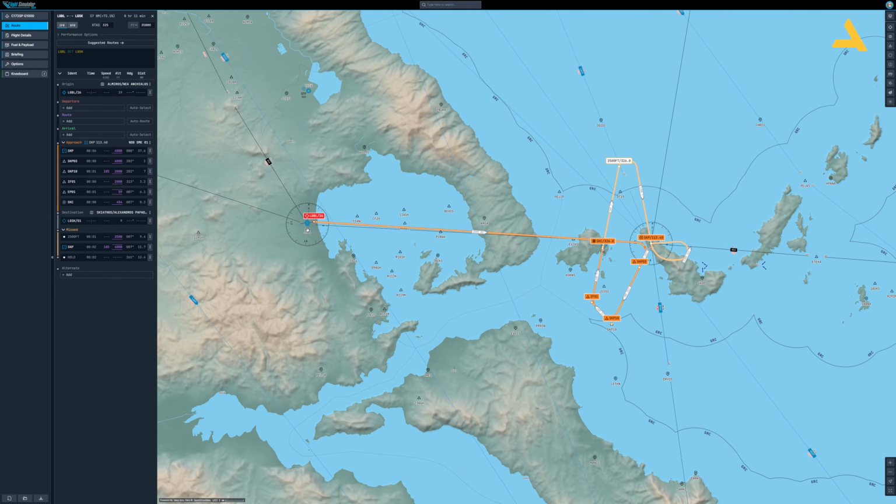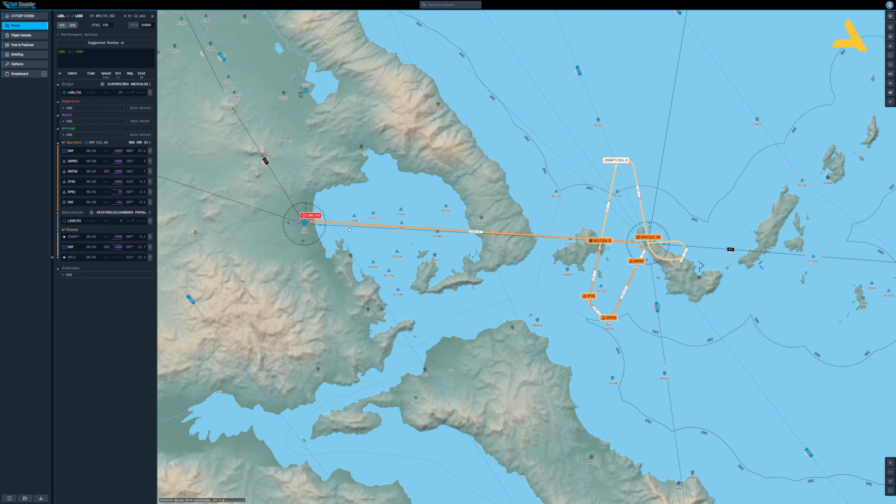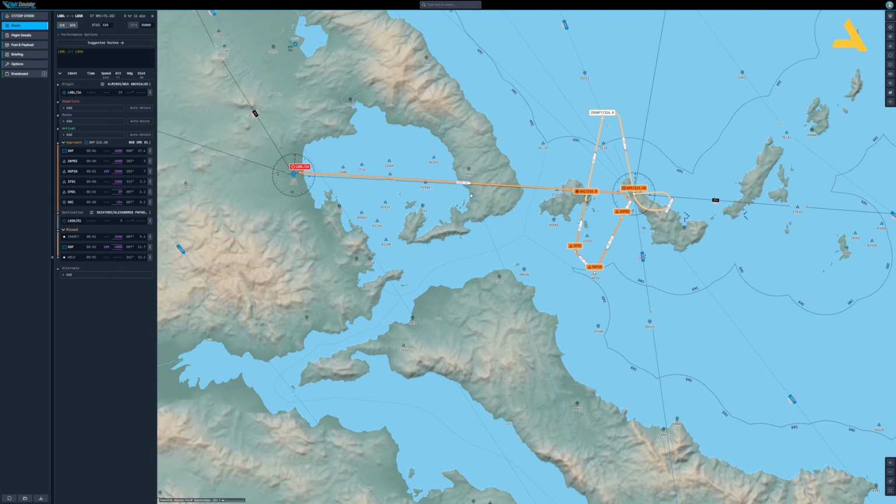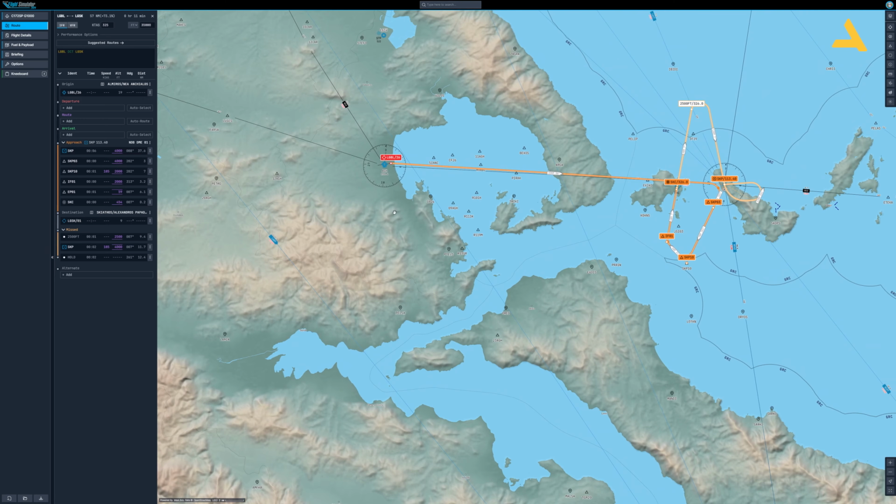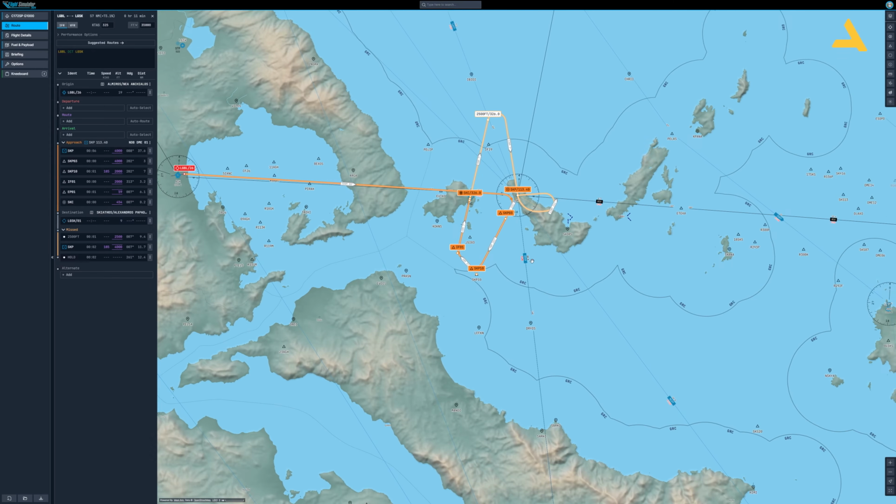Let's say if I take off and turn left, and then start traveling in this direction, 88 degrees, then obviously I'm not on this line. This is known as the radial, the outbound radial for this VOR. And similarly, if I deviate from the course and start traveling 88 degrees from over here, then obviously I will be missing this VOR. So I will be somewhere here.